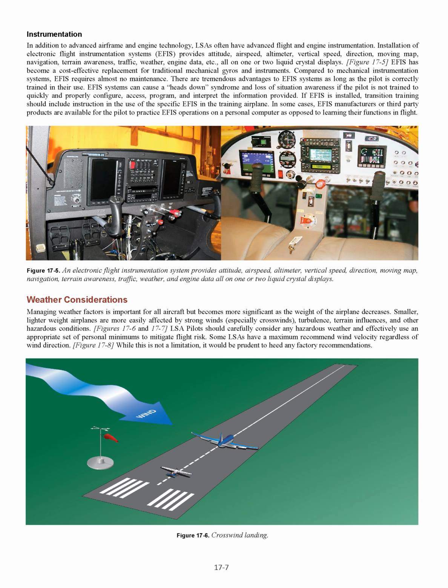Weather considerations. Managing weather factors is important for all aircraft but becomes more significant as the weight of the airplane decreases. Smaller, lighter-weight airplanes are more easily affected by strong winds, especially crosswinds, turbulence, terrain influences, and other hazardous conditions. LSA pilots should carefully consider any hazardous weather and effectively use an appropriate set of personal minimums to mitigate flight risk. Some LSAs have a maximum recommended wind velocity regardless of wind direction. While this is not a limitation, it would be prudent to heed any factory recommendations.